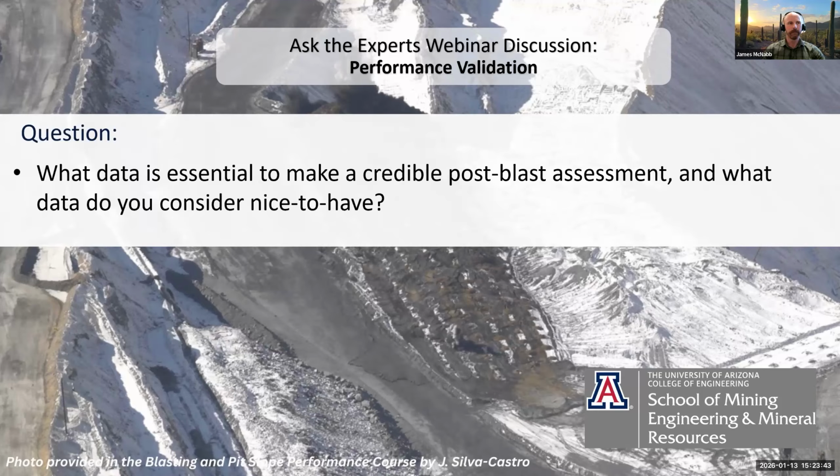Second point is that after the blast, you want to be able to have a look at the blasted muck pile, looking for things like powder trough, excessive heave, any obvious areas of poor fragmentation, and see how that relates to your planned initiation sequence and result.